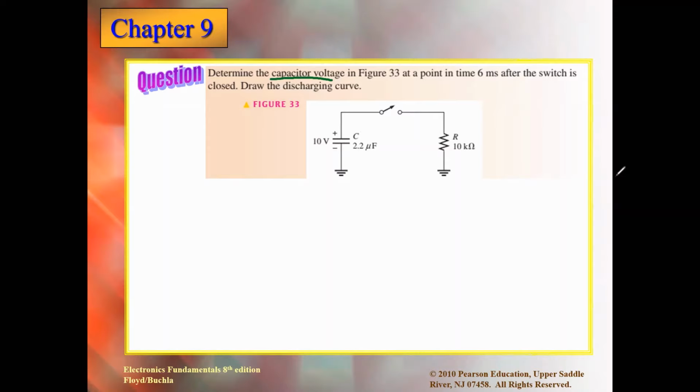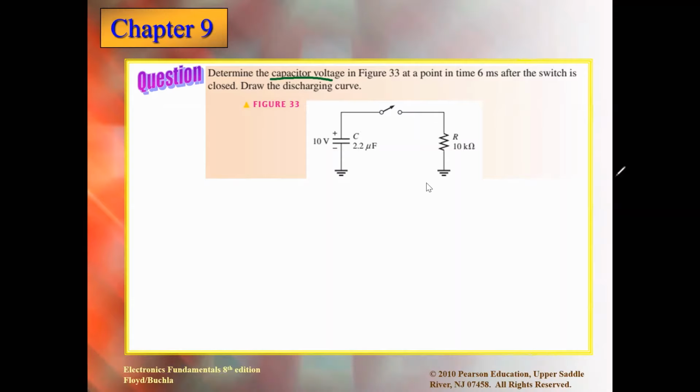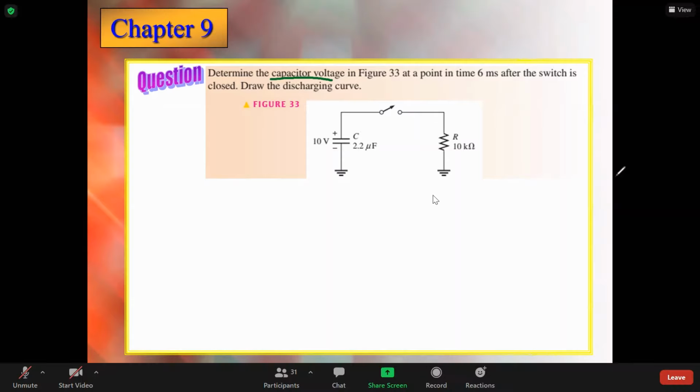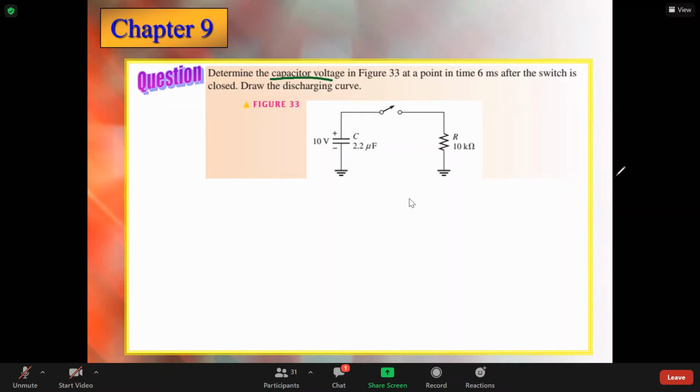The point is this adapter, even if it is your mobile adapter or laptop adapter, converts this AC into DC. So it is an AC to DC converter. How does it do this? We need a capacitor. Over there, the capacitor is used as a filter to eliminate the AC component.